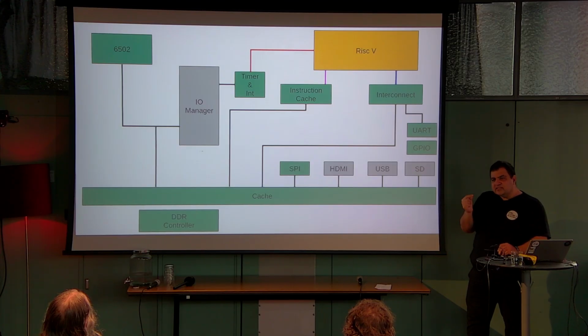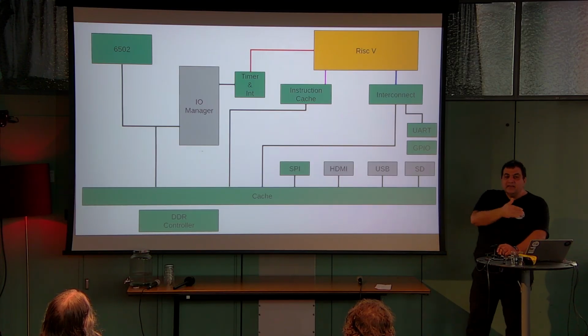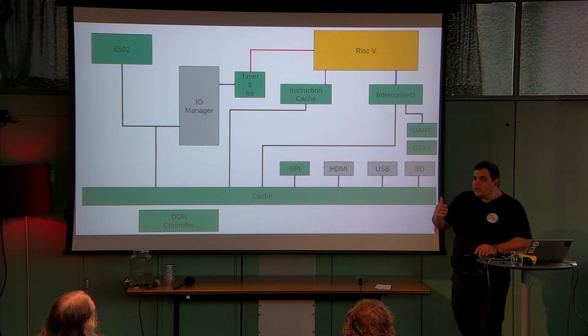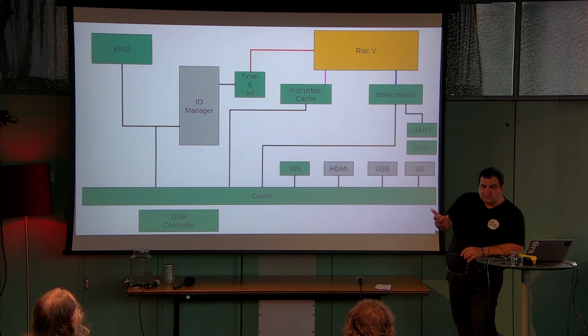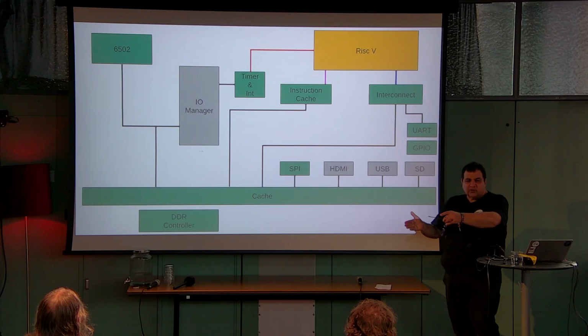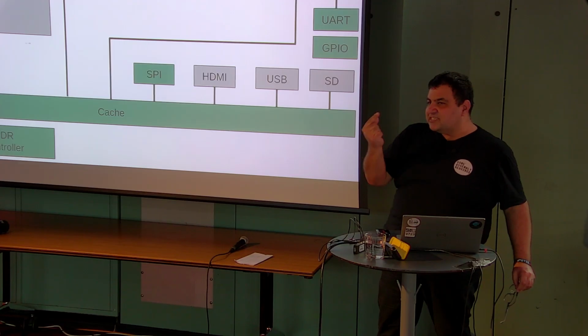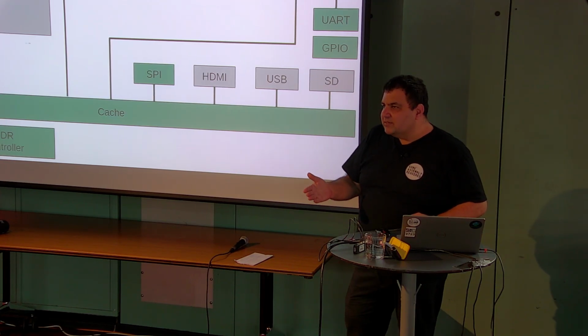And then the RISC says, OK, I know what that address means, and handles the I/O side of things. And this way, a lot of the hardware that the 8-bit needs becomes software, which doesn't cost me logic on the FPGA, it costs me memory. But remember, I have 256 megabytes of memory. So no shortage of that.